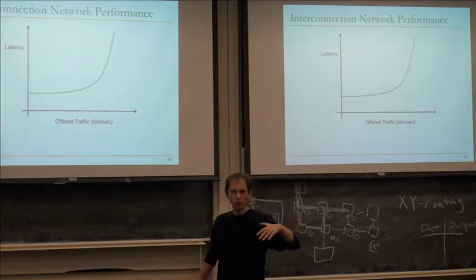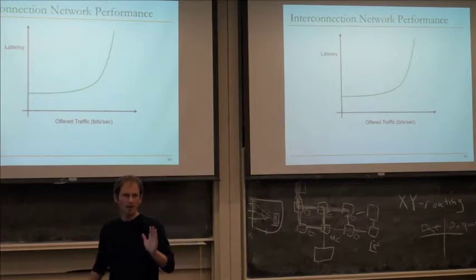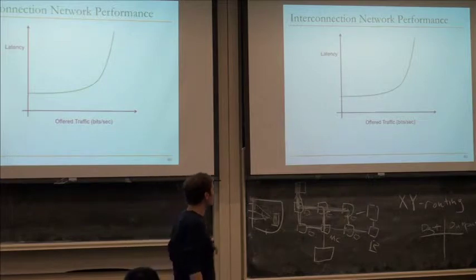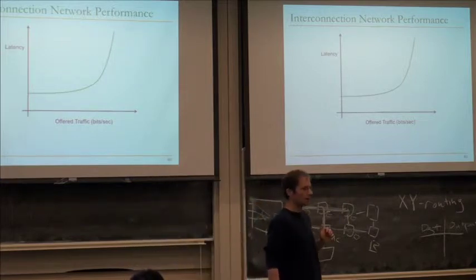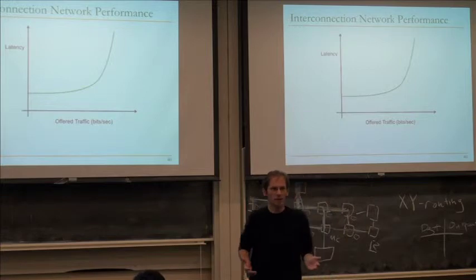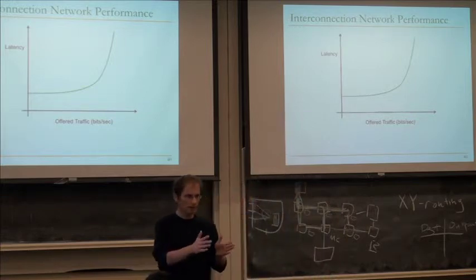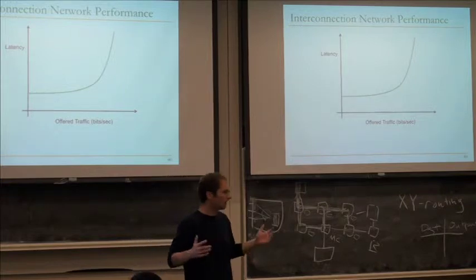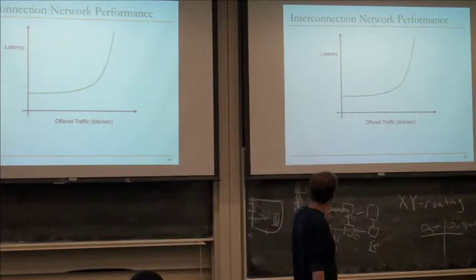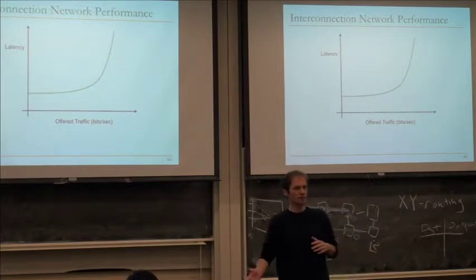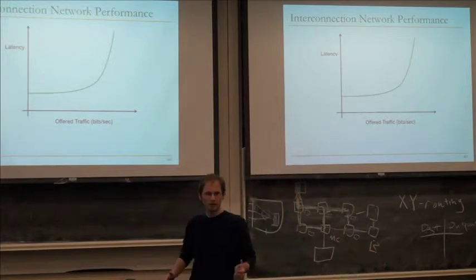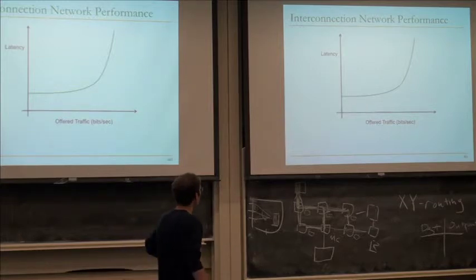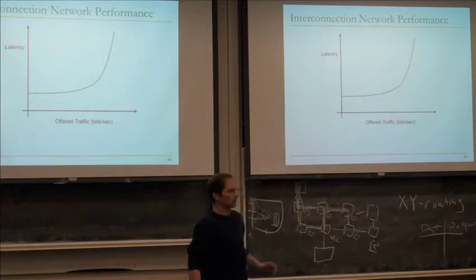And then in the limit, eventually you'll hit this point where the network saturates. This is where the latency curve shoots up, and that's where your offered traffic is approaching the actual network design capacity. So, in the best case, if you have a 1 flit width into the network at every router, that would be 1 flit worth of bits per cycle per node. Usually it saturates below that because there are inefficiencies in the network. There are overheads with things like head flits, there's overhead with routing, and there's overhead with contention effects that make it non-perfect. But there should be some point where the network saturates.